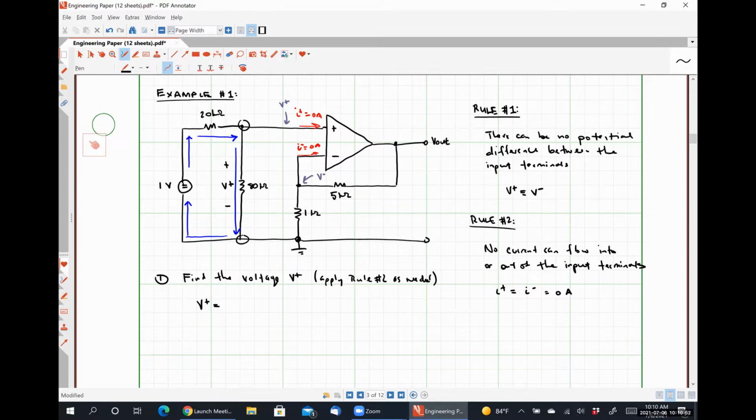All right, so you're both close. The first suggestion was a little bit better. The second person who spoke said that we would divide 1 volt by 20 kilo ohms to get our current. The problem with that is assuming that there is exactly a 1 volt drop over the 20 kilo ohm resistor, meaning that we were assuming that that node is ground, and we have no reason to assume that. We don't know that 1 volt drops over the 20 kilo ohm resistor.